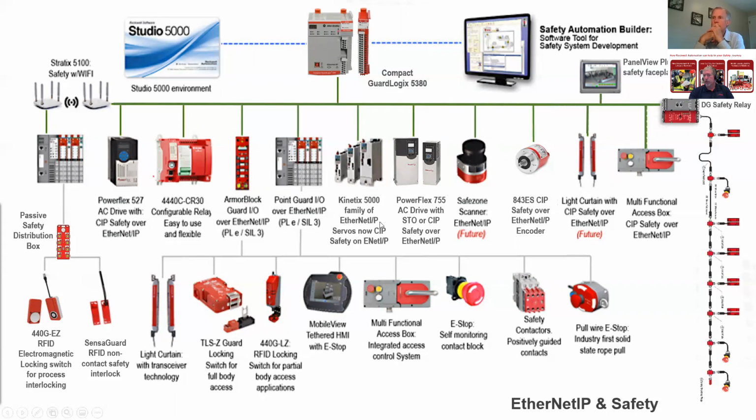And again, into the drive world, where you can do CIP safety directly to Kinetix family of drives, to the 755 drive, depending on what option card you put into the drive. CIP safety encoder, CIP safety multifunction access box, and two products that are near future, say before end of year is what we're being told, which is EtherNet/IP direct connection CIP safety scanner, EtherNet/IP direct connection CIP safety